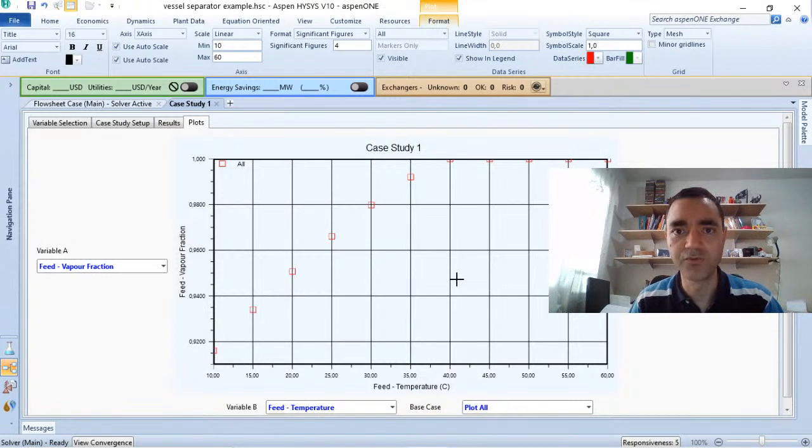And if the formation of condensate is too critical to your process, we can set that at 40 Celsius degree the station should be shut down, because if I form liquid for any reason, I will need to pay thousands of dollars because I didn't comply with the requirements.